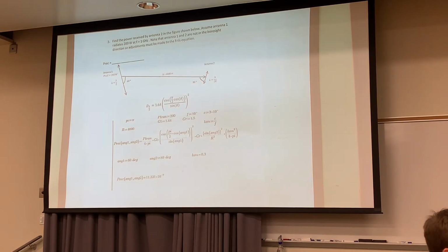Do you mind explaining this a bit? 'Cause my understanding was it had to be above the cutoff frequency. It is. Okay. The cutoff is what? I meant below. No, above. It's a waveguide, only high frequencies pass in a waveguide. So if you take the long dimension A, well, A is lambda over 2, right? So 2A is lambda, lambda is c over f cutoff, and you can calculate f cutoff is c over 2A. Now if that's the cutoff, if 4 gigahertz is greater than that, it propagates. Okay. I got it the wrong way around. It has to be higher than that to propagate.